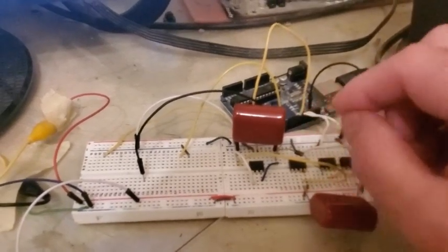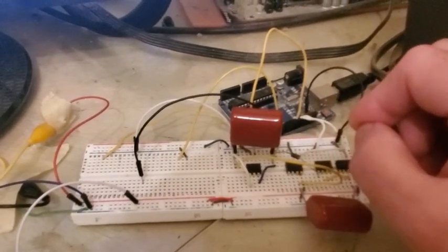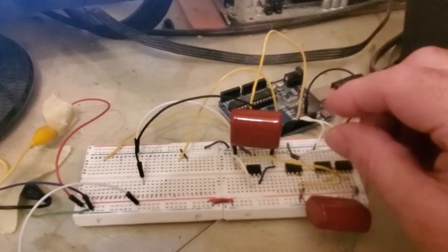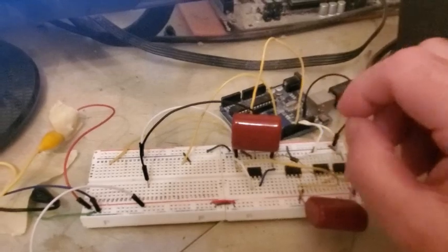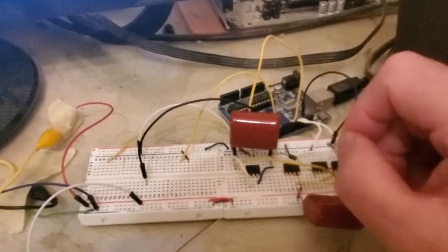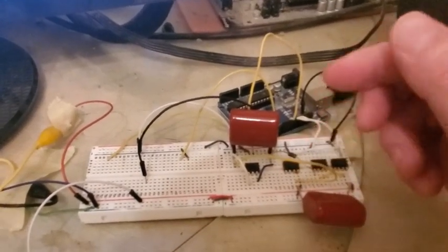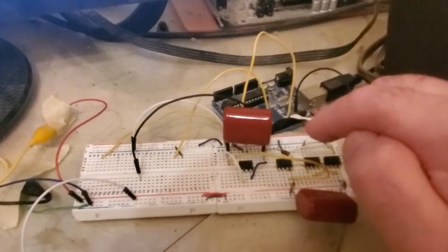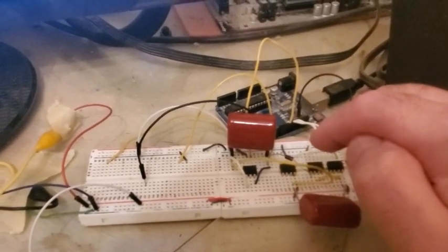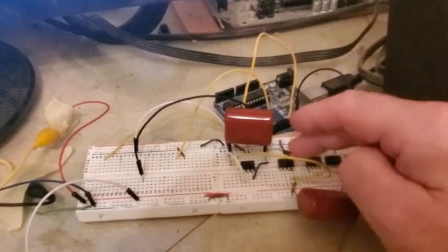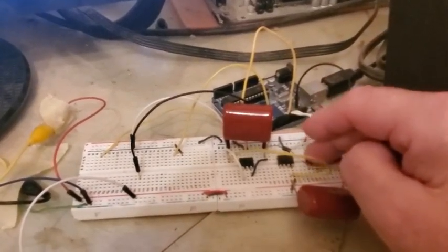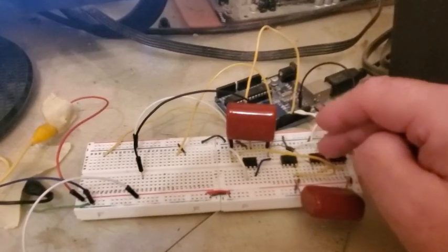They have about 1 or 2 ohms of resistance in the on state, which you say, well, that's nothing. But what if your coil has 1 ohm of resistance? Now you've doubled the resistance, and you're trying to get the resistance low. So you don't want a coil with 50 ohms of resistance. You want a coil with 1 or 2 ohms of resistance. And then that 1 or 2 ohms actually, I'm thinking, will be a big deal.